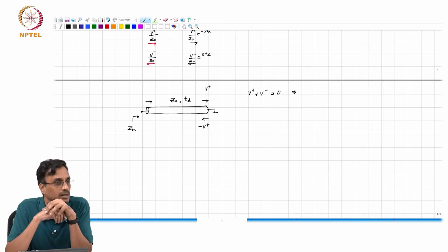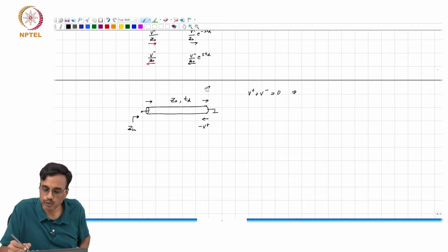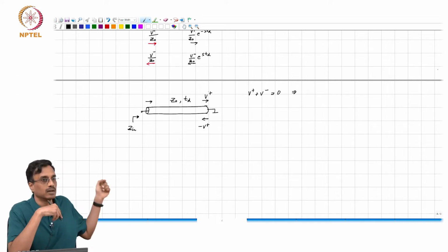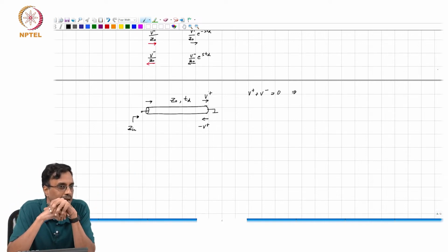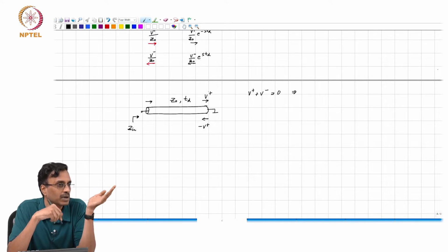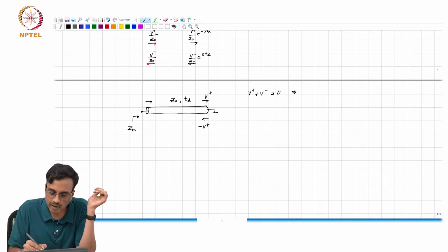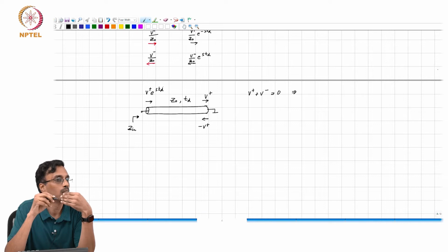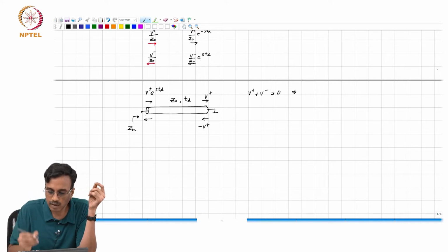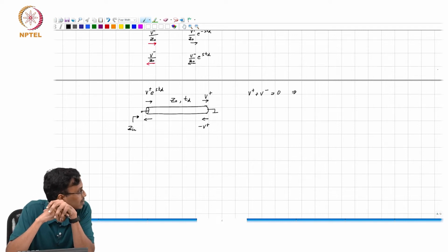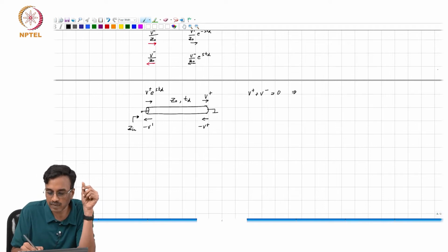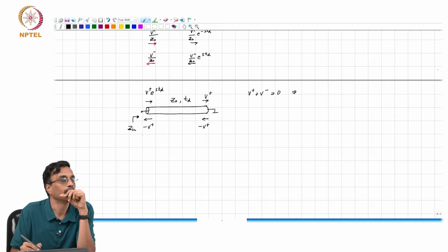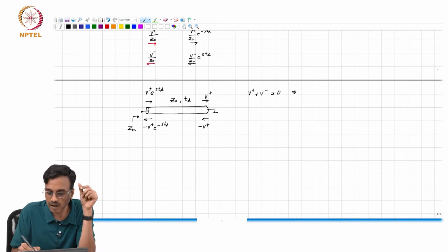So, alright, if this forward going wave is V plus, what comment can you make about the forward going voltage wave there? The voltage on the right is V plus, it's going this way. So what must be here at the left end must be an advanced version. So that basically is V plus e to the s times Td. And likewise, the backward going wave must be minus V plus e to the minus s times Td.